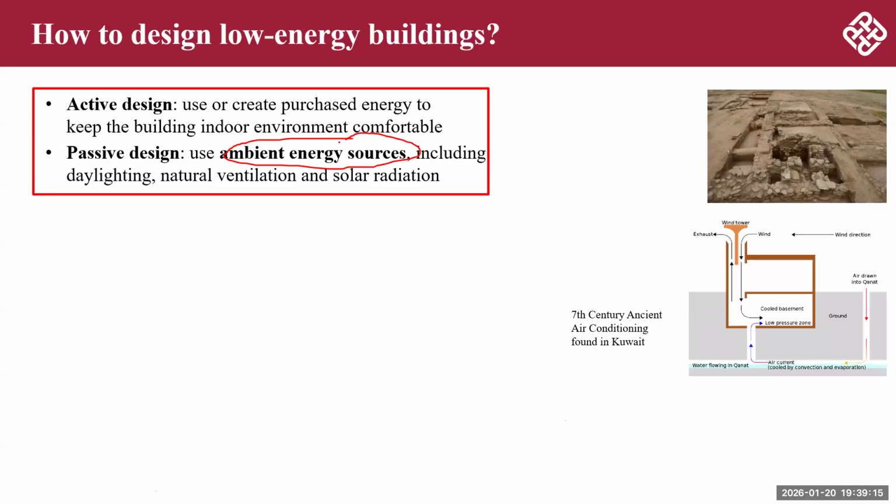Because it is dry, the water vaporizes, and this vaporization process will cool down the surroundings. So the warm, hot, dry air will be cooled down and also humidified. Then the heated, warm air is light, so through the chimney effect, it circulates natural air ventilation.